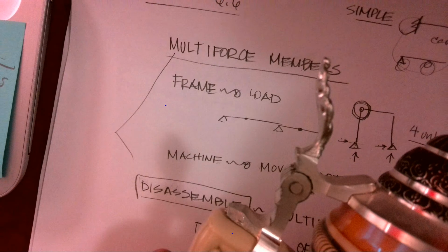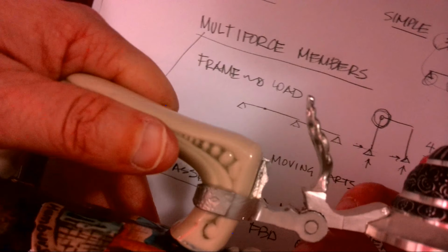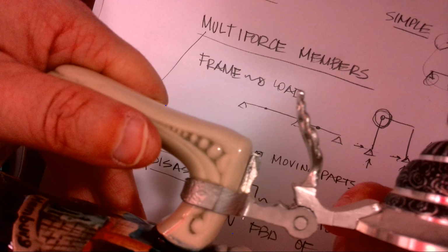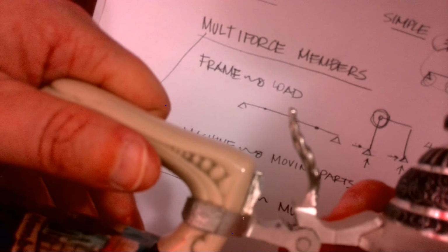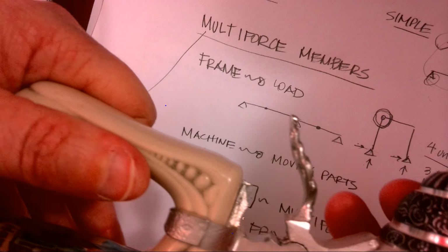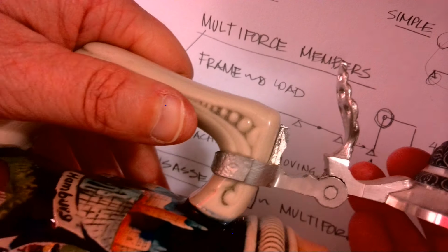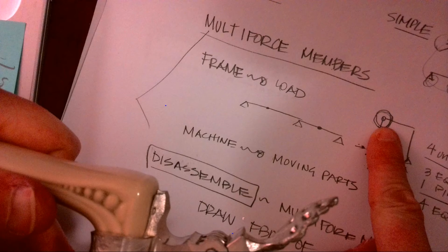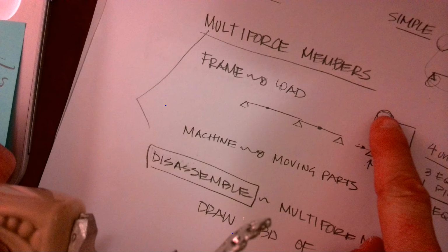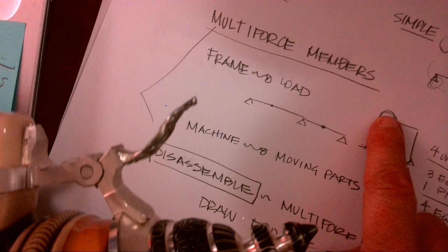Okay, when I look at that pin, I'm going to try to go slow because I'm going too fast for the camera. If I try to pull this apart, the lid off the bottom part here, that pin is resisting that internal force. So if I try to push the lid up and the stein down, again, we're resisting the force in the X and Y direction, but we have rotation. That's what this internal pin right here allows us to do. It's going to resist X and Y. It's going to transfer a normal force and a shear force, but it would allow rotation.